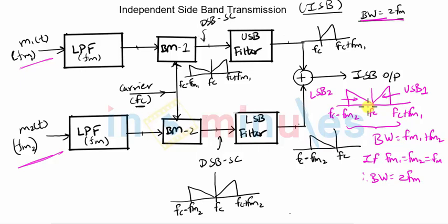One drawback of this whole system would be that whichever receiver you have which is tuned to the carrier frequency can easily receive both the sidebands, and hence it will have information coming from both the modulating signals. You can't make a receiver receive only the upper sideband and demodulate only M1(t), or receive only the lower sideband and demodulate only M2(t). So only when you are fine with the receiver receiving both the modulating signals that you have attached can you use independent sideband transmission.